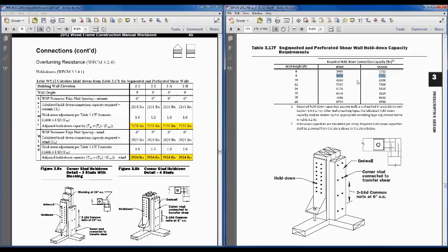We certainly would not prohibit an engineer from designing, assuming the actual loads on the wall and spreading those loads out across the length of the wall. It does make it a little bit difficult to offset those hold downs with dead load, and so we're also not offsetting hold downs with dead load because it's hard to determine tributary area for offsetting dead load. There's a lot of engineering judgment assumed in that approach.